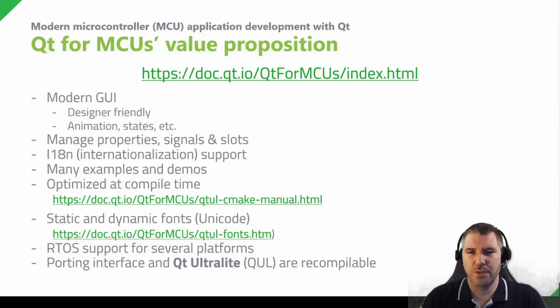Unlike the Qt framework, Qt for MCU optimizes your code at compile time. There is no script engine, so the QML code is compiled through C++. You can also give hints to CMake to choose compression, cache, RAM and flash location preferences for your application assets.